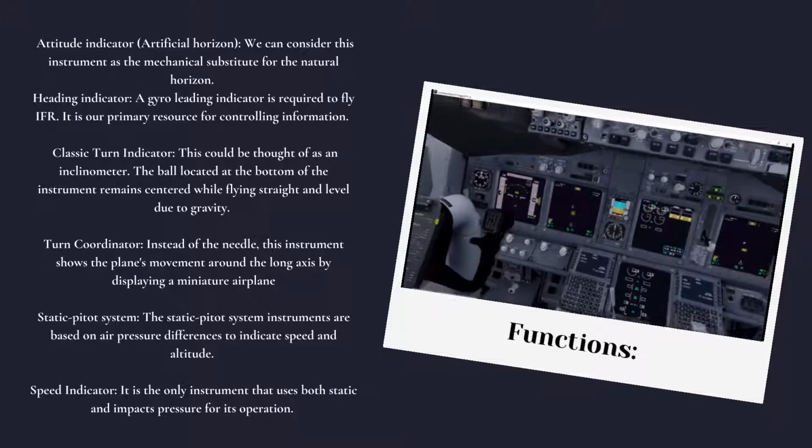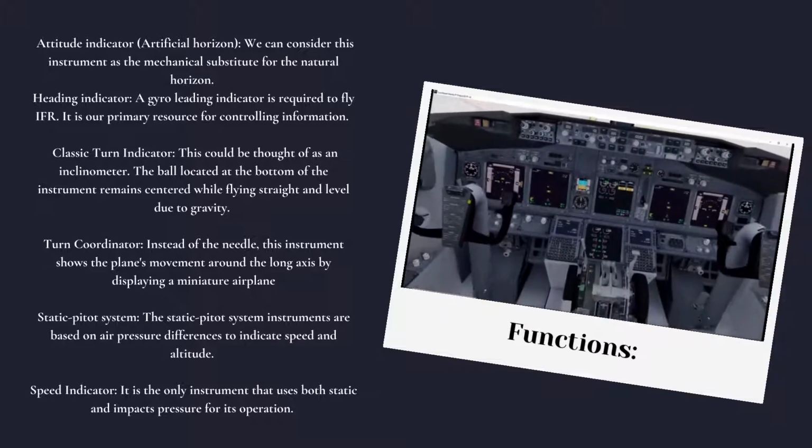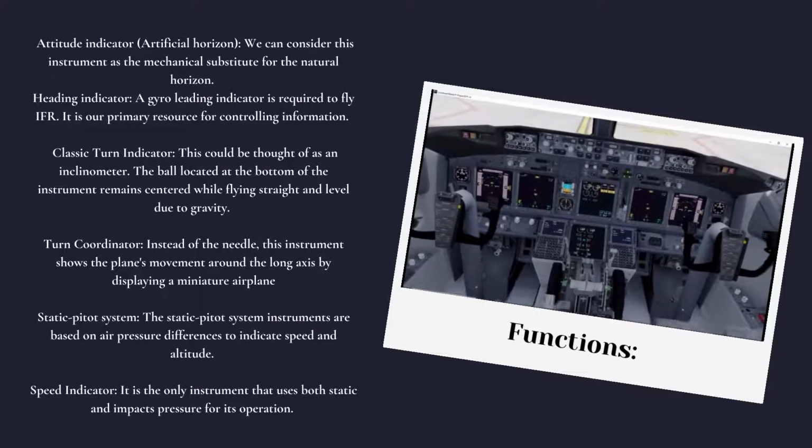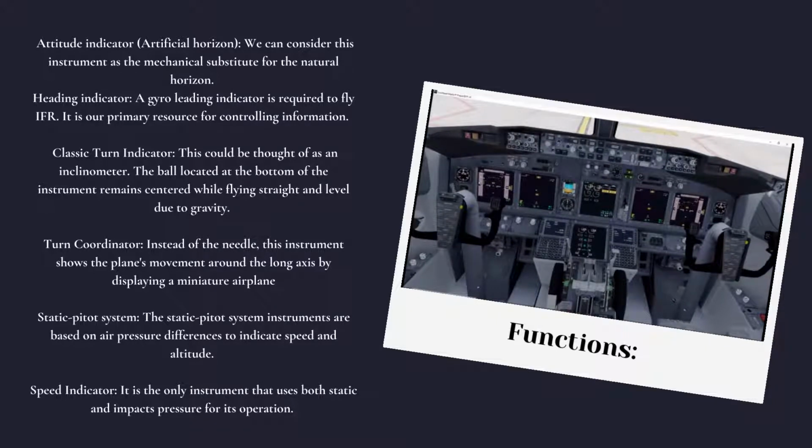Heading indicator. A gyro heading indicator is required to fly IFR. It is our primary resource for controlling heading information, since course changes in a coordinated flight imply that the wings are not level. We can indirectly say that it indicates bank.